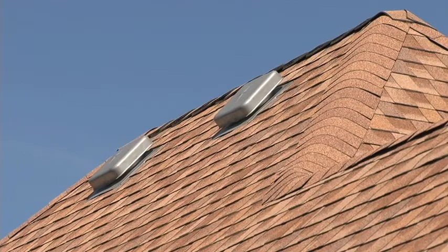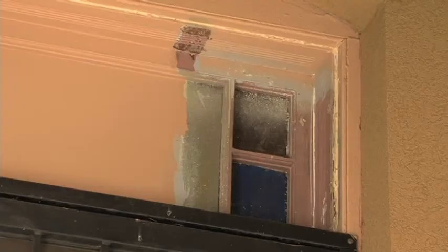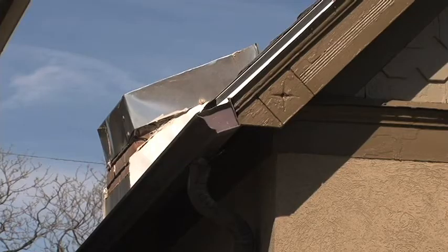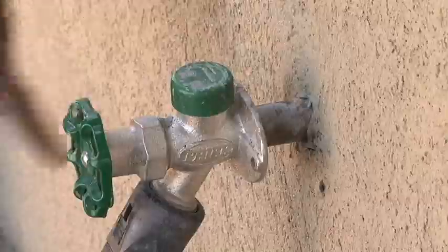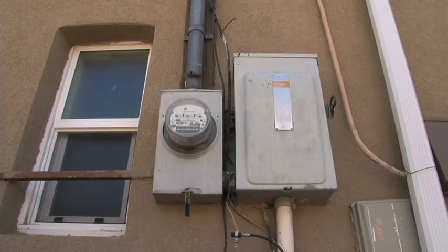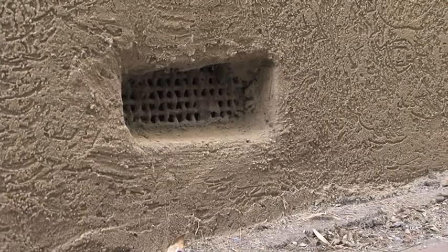We're going to take notes of attic ventilation, including our soffit vents. We're going to be looking at the windows, make sure that we have windows that are tight. What kind of condition are the windows in? We're going to be looking at building penetrations. Do we have hose bibs, plumbing penetrations, electrical penetrations, cable penetrations, and are those penetrations sealed? Do we have vents into the house or into a basement crawl space area?